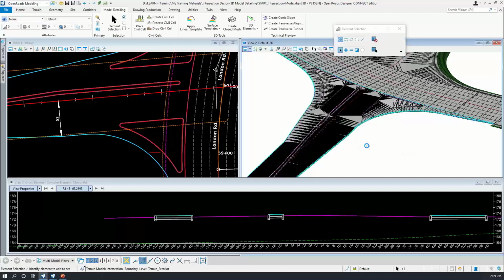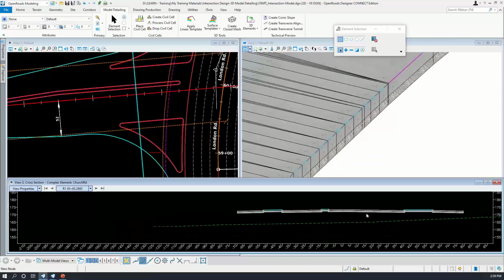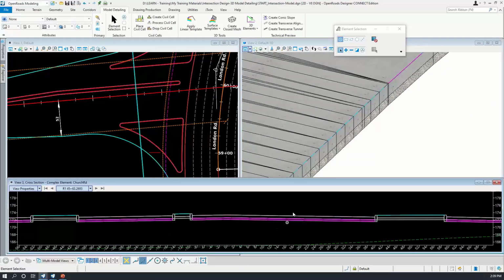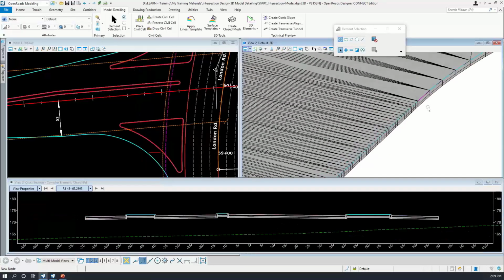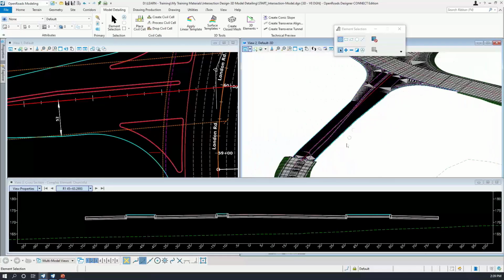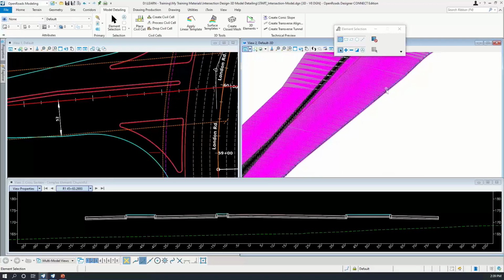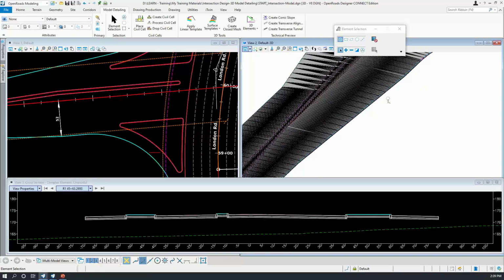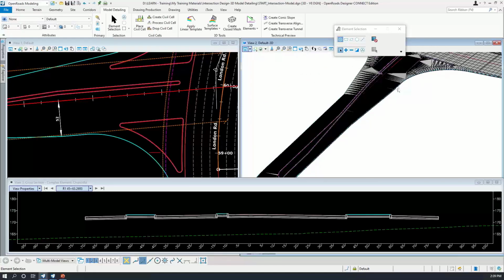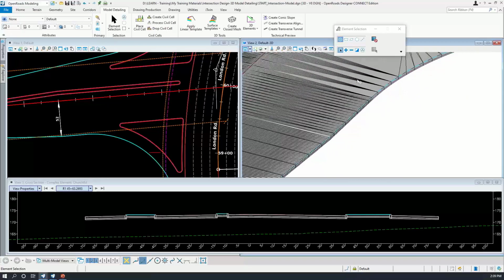Let me just use the same surface template, and then there you go. From here, you now see the cross-section building up. Now to finalize this, although I'm not going to finish it all, I'm going to apply a linear template on this side of the road so that I can show you how the curb, gutter, sidewalk, as well as the cut and fill are done.